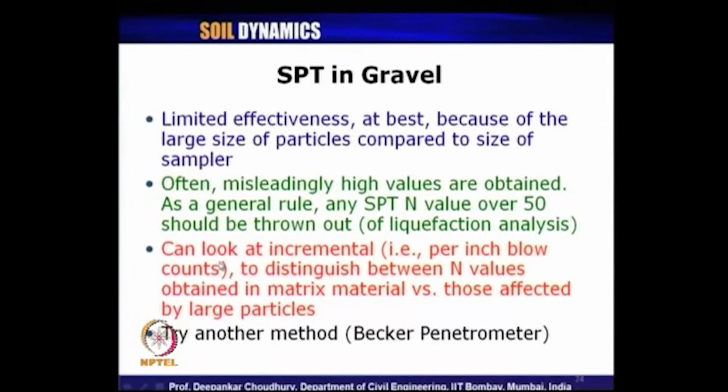We should also look at the incremental, that is per inch blow counts, to distinguish between N values obtained in matrix material versus those affected by large particles. What does it mean? Whether the SPT N value greater than 50 is truly representative of the entire soil, or only because of some pockets where a large particle suddenly appears.